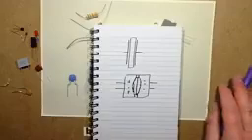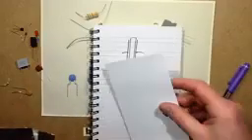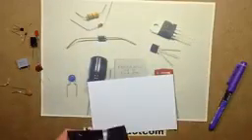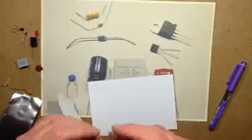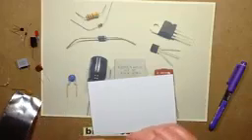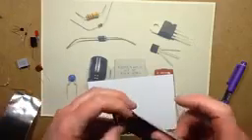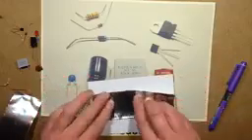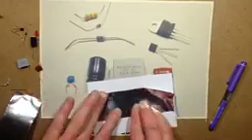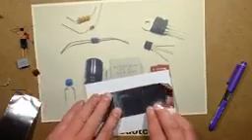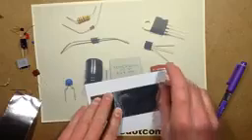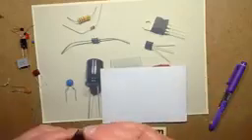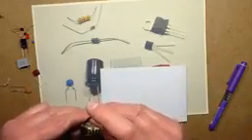So I've got a bit of cardboard here. This is a standard 6x4 piece of photo material. And I've got 2 bits of metallized film. So let's stick the metallized film on either side. So we've got a metal electrode and I'm sticking it onto the insulator, the dielectric. And this is old aluminium tape, I think, because it doesn't seem to stick very well. But that's alright, it'll do what we need. And then on the other side I'll stick the other bit of tape, and that's the other electrode.